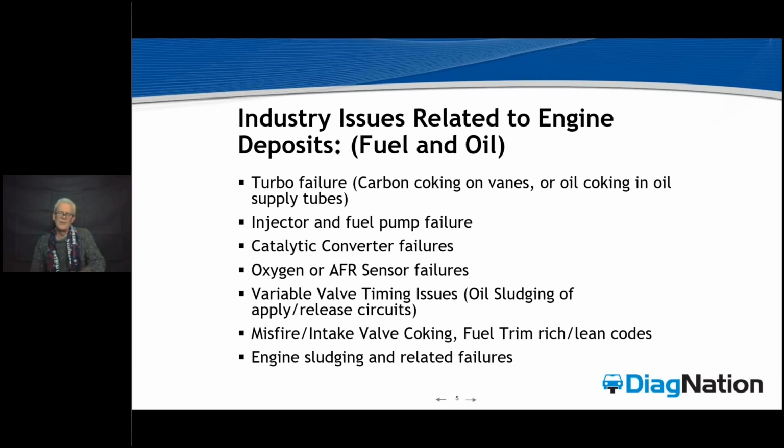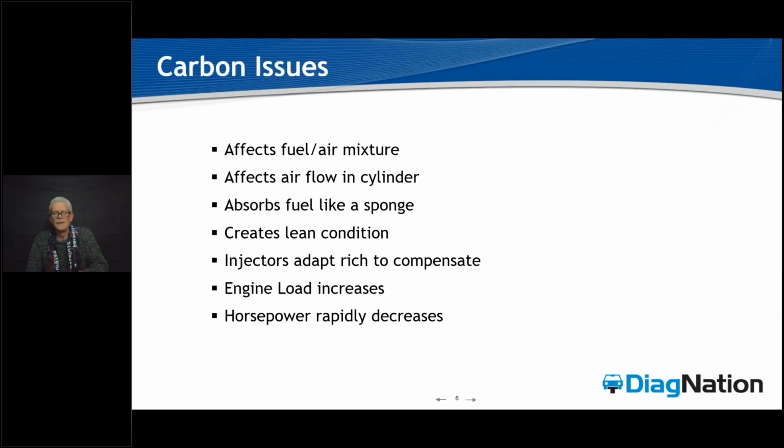What you're going to see here as this unfolds is that the biggest consideration, in my mind, for why these engines build up fast is the drive cycle of the car. What I mean by that very specifically is a customer, let's say that, for example, in this area might be what I call a short tripper, okay? And what that means is he's driving 5 to 12 miles each way to work every day. And worse than that, he's sitting on the beltway. And because of that, that car is what I call a short trip, stop and go city driver car.